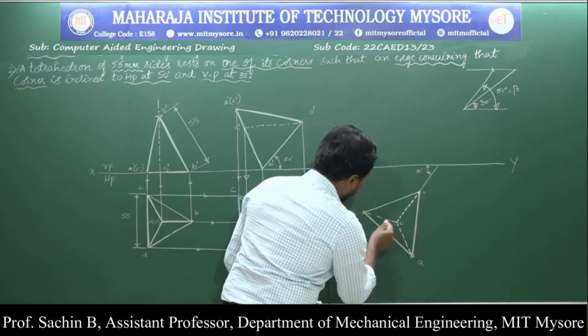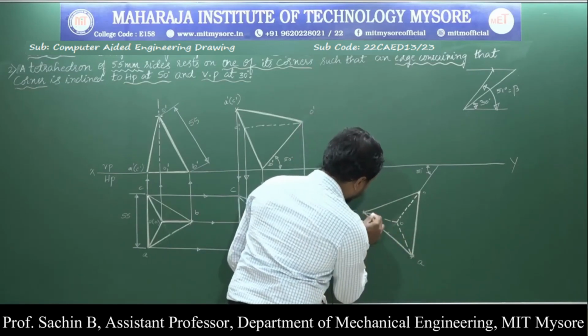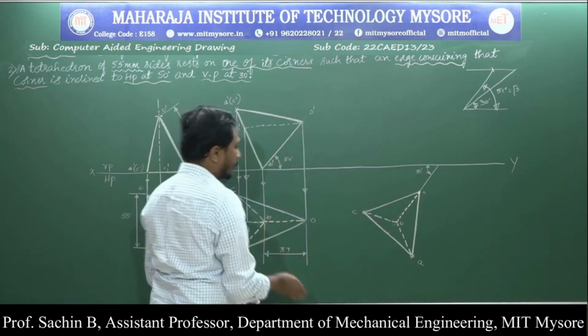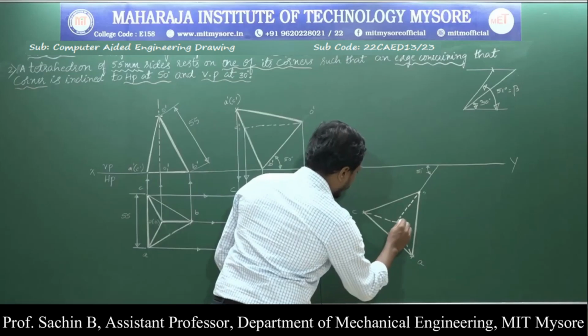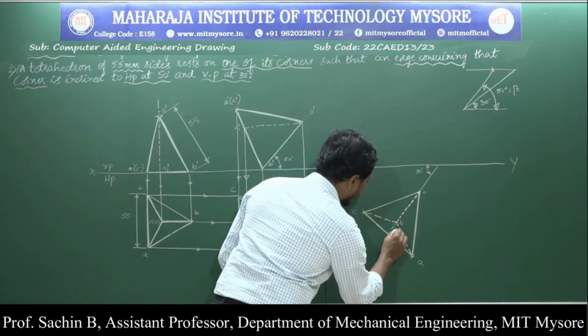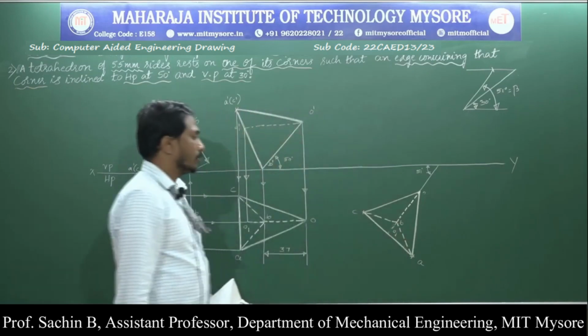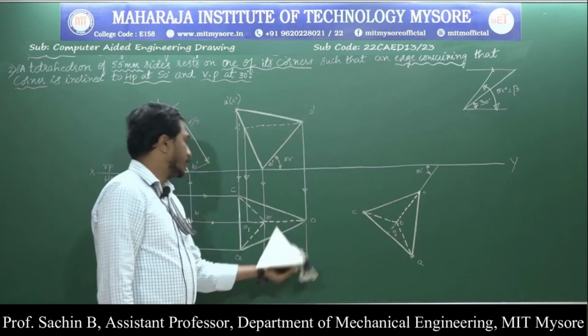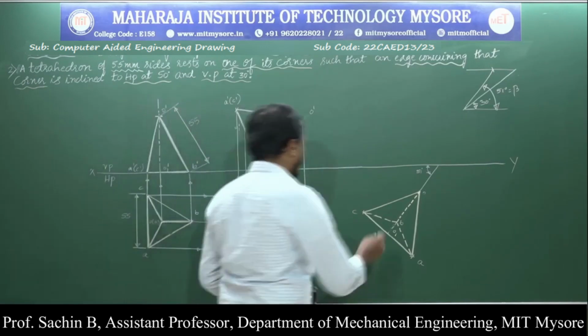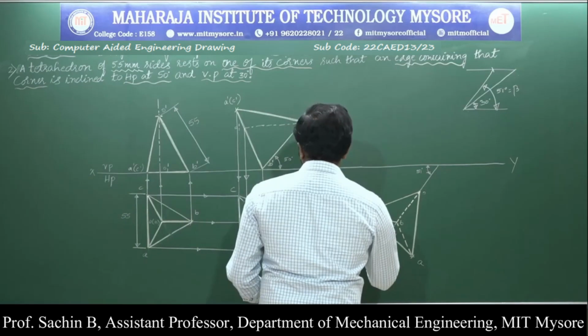Next, the axis representation is required for us. Similarly, I am going to measure it from B to O1. I am going to mark the axis here with the chain line. This is my O1 point. Now, I have transferred this second position to the last position. Next, I will go for drawing the projection line from all the corners.